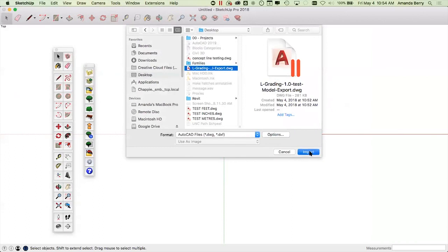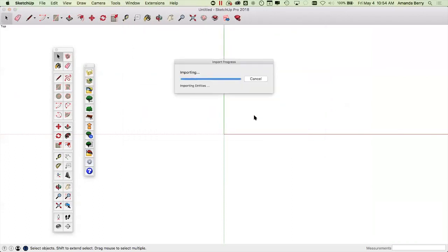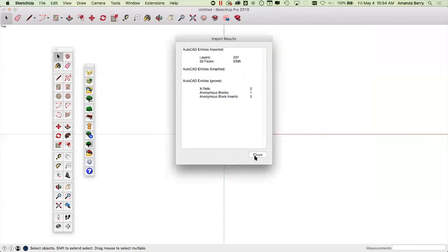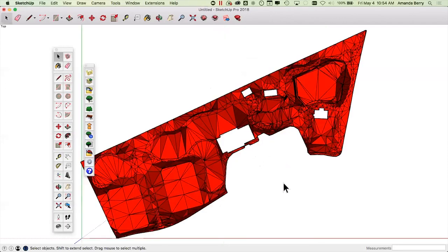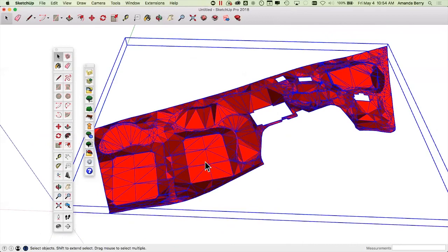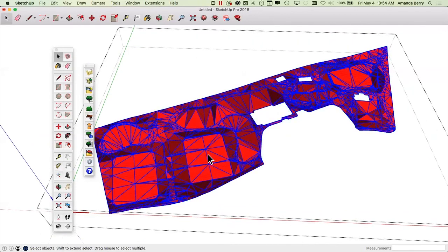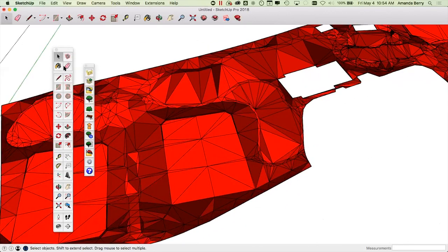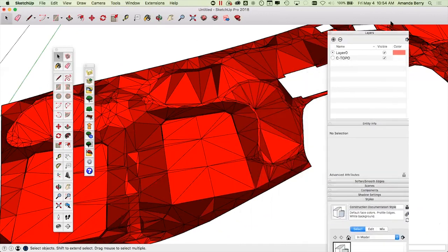It goes through. It tells you what it did, and it has a face. And then basically all I did was it makes it into a block. I went in here and popped that all over to, say, grass. And then I went in here with my erase tool. You could just turn off edges at this point, even just in settings, you could save a bit of time.